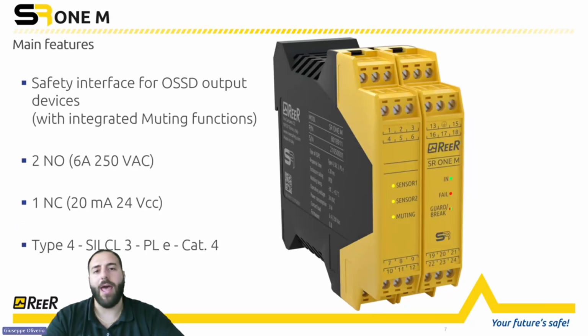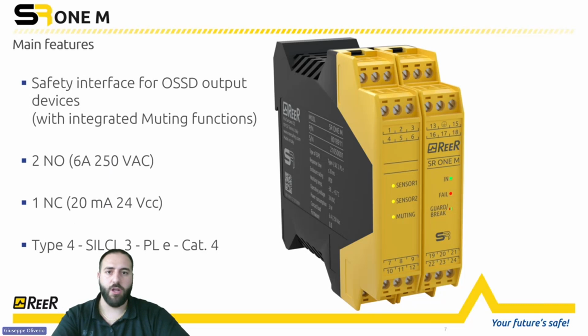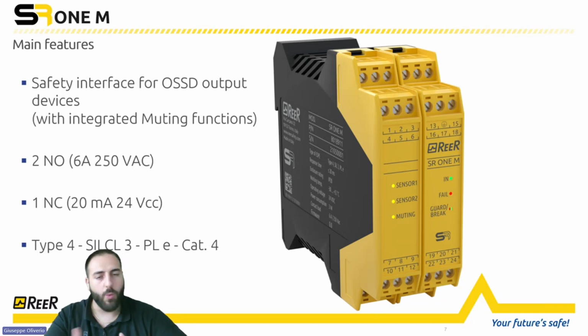The SR1M is basically the same as the SR1 plus the muting integrated function. So in order to do a muting logic with two sensors across a beam, for example, that is one of the most common muting logics, then the SR1M is the right solution. Of course, again, you have to connect the light curtain, sensor, and interface.